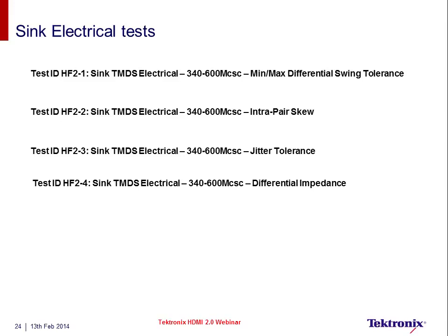This increases the test times because there is human intervention in order to insert the 112 picosecond delay line first on the positive lanes, complete the test, remove it, and put it onto the negative lanes before we can complete the test. So that is inevitable, and we are trying to see how best we can make the whole testing environment much better. Hopefully you will hear more about the complete automation capability using the software capability of the Tektronix direct synthesis. For now, the cable emulator is directly synthesized in the AWG, while we need to use the hardware 112 picosecond delay line.